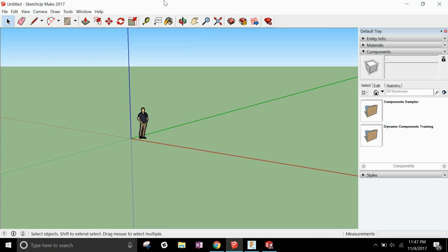So as you can see, we have an environment where we can go up and we can actually make 2D sketches. As you can see, I'm just dragging a line here. And if I enclose, for example, a 2D shape, like I did there, I can actually go ahead and do what's called extruding.